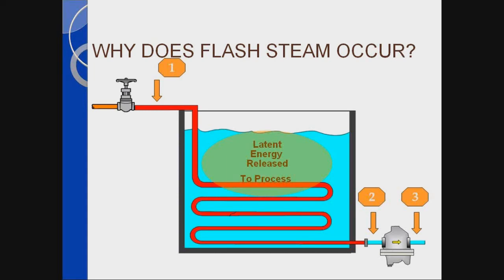As condensate passes through the orifice of the steam trap, it sees a lower pressure. Let's say that is 0 psig; the condensate temperature has to come down to 212 degrees. How does the liquid get its temperature down to 212 degrees? It takes a percentage of the liquid and changes its state from liquid to vapor, or flash steam.